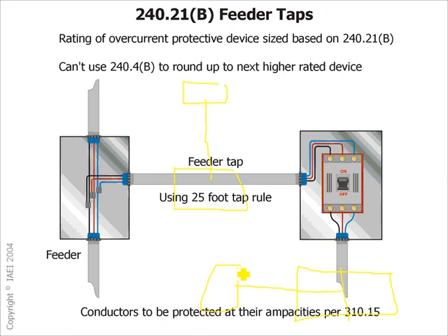So what you're doing here basically is you're tapping here and doing control, and whatever you're doing here. These tap conductors are not leaving the enclosure. Then you can even go less than 1/10, and that's what you're dealing with, because the fuse on the end of that little tap is protecting that short length.